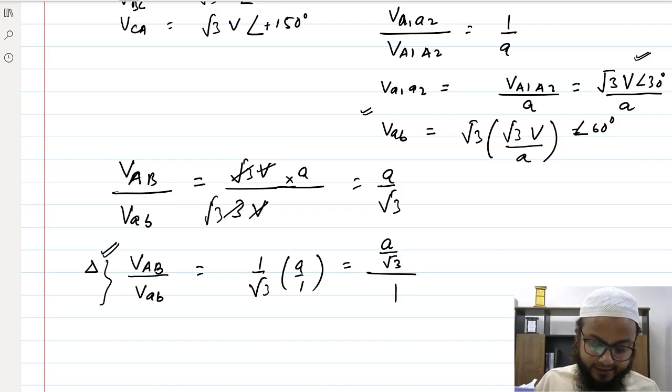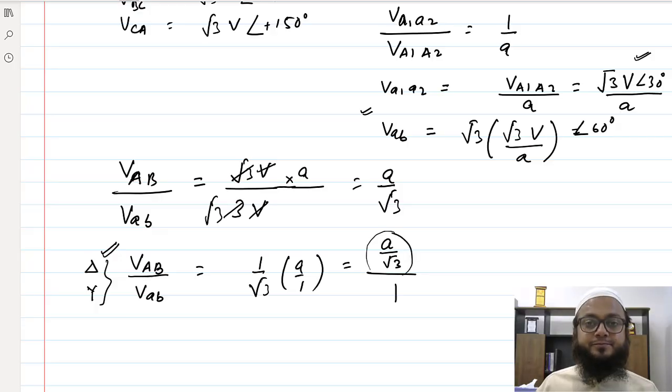And the star side, if you'll see, is at 1. This is the star side, right? So on the delta end, you can see the turn ratio is inherently getting reduced. Okay. So at the transmission level, we use this delta star.